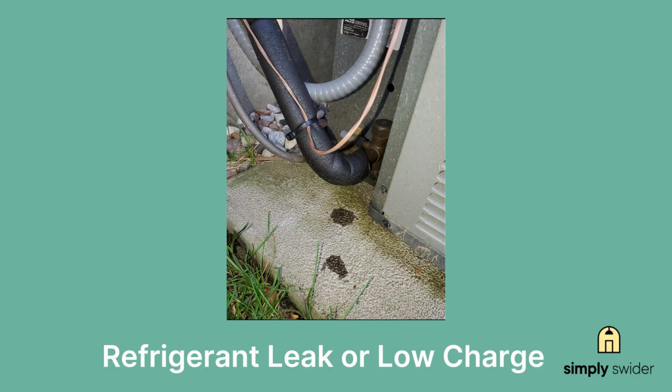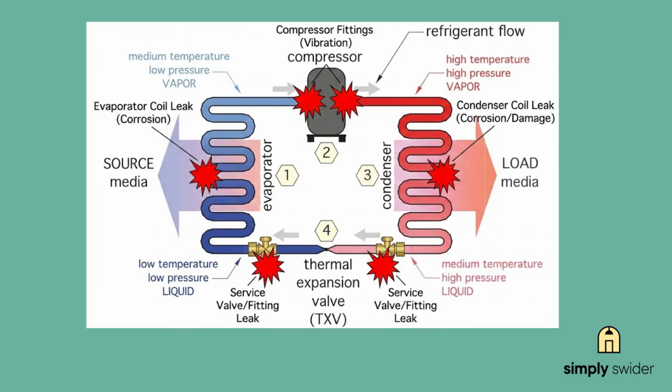So the most common cause is going to be a refrigerant leak or low charge. Here's what happens. You don't have enough refrigerant mass in the system, so that indoor coil never gets cold enough to satisfy the logic. I had this customer last month who called me panicking because her unit was blowing warm air and showing C422. Turned out to be a tiny leak at one of the flare connections. Vibration over 3 years had worked it loose.